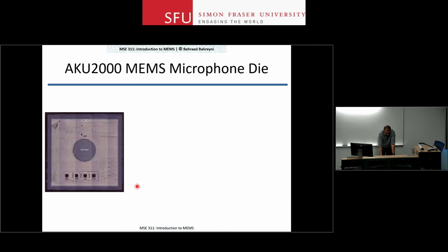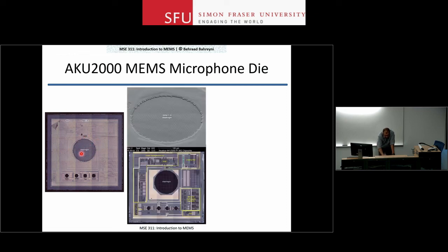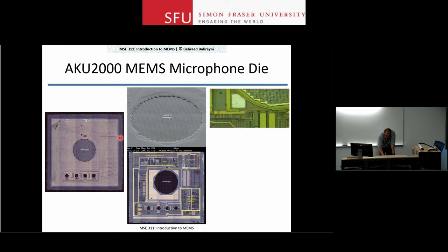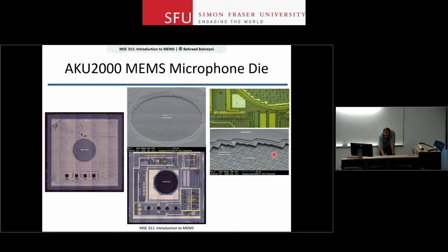So here is an example of a device. This is where you have all the electronics. In the middle of the chip, you created those structures. Let me show you a close-up view. This is made by patterning the metal layers in this kind of configuration. The reason they're doing it like this is so that they release the stress inside those metal layers.